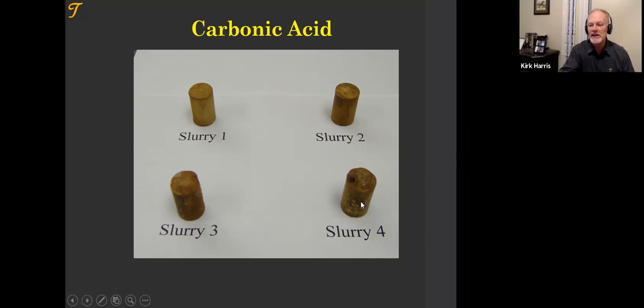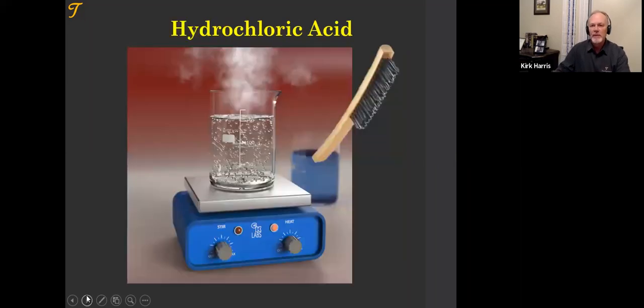I don't know if you can see more of a pitting of the cement in certain cases more than others that are more acid resistant. But we don't put these in carbonic acid and they just fall apart. There is a dissolution and a selective pitting. And the way we design around it is very interesting to avoid the CO2 causing corrosion.